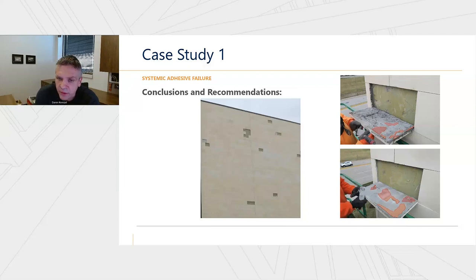They're included in a lot of the industry guides, and Renae is going to dive a little bit deeper onto those in a bit. So our takeaway on this, of course, important to follow manufacturer's instructions and code and get that mortar squeeze out the perimeter, and all of that would have mitigated the water that gets to the backup and deteriorates the adhesive bond.